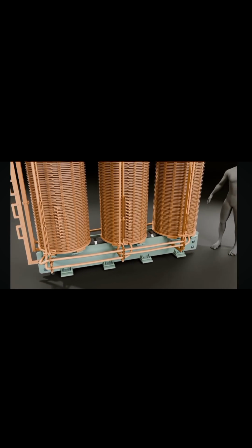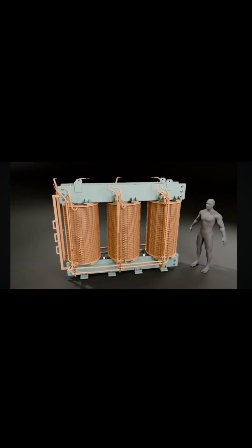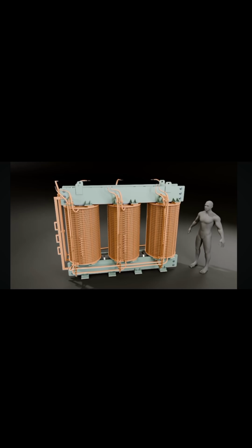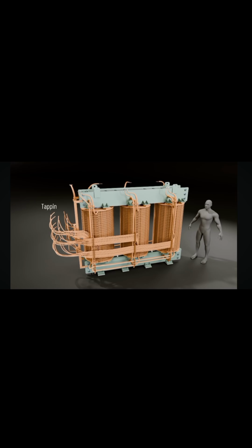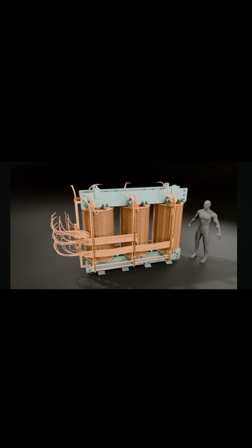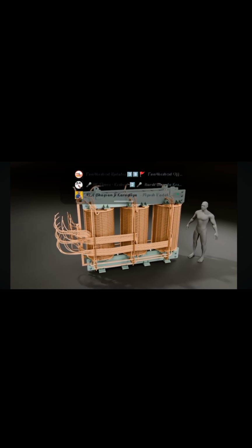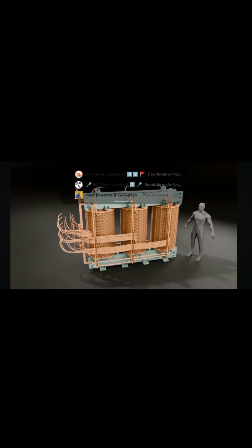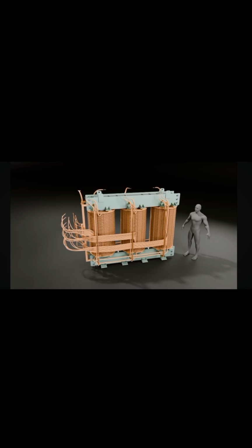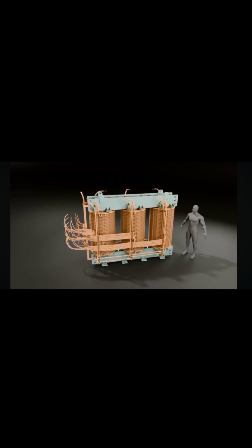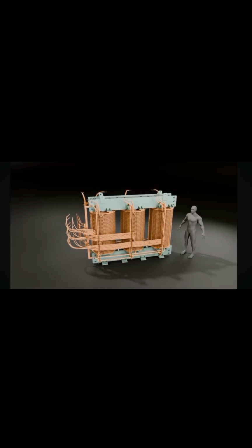Almost all power transformers require adjustment of their voltage ratio to operate effectively under variable load conditions. This is achieved by adjusting their transformation ratio using tappings. Tappings are placed on the high-voltage winding because the high-voltage winding is more accessible, as it is positioned outside of the low-voltage winding. Additionally, the lower current in the HV winding simplifies the process of switching between different tappings.